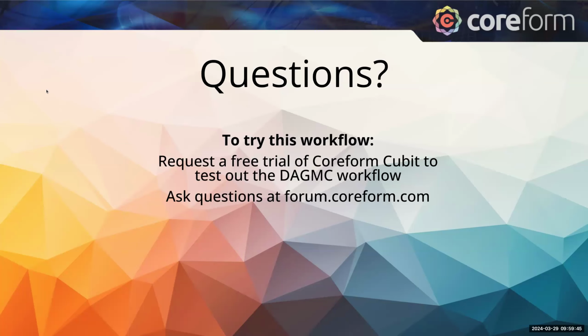Yeah. Great. Okay, looks like Brian has a little bit more specific clarification on that other question. Patrick, if you want to respond to that. Oh yeah, I see. Okay, I think I understand, Ryan. So what Ryan was trying to get at is that using an unstructured mesh tally or a tally with DAGMC is much better for complex components, because for something like a regular mesh, it's not guaranteed that your tally mesh elements are going to be conformal to the geometry necessarily. So the ability to use something like an unstructured mesh or even do this representation in a CAD-based geometry itself is advantageous. Great.